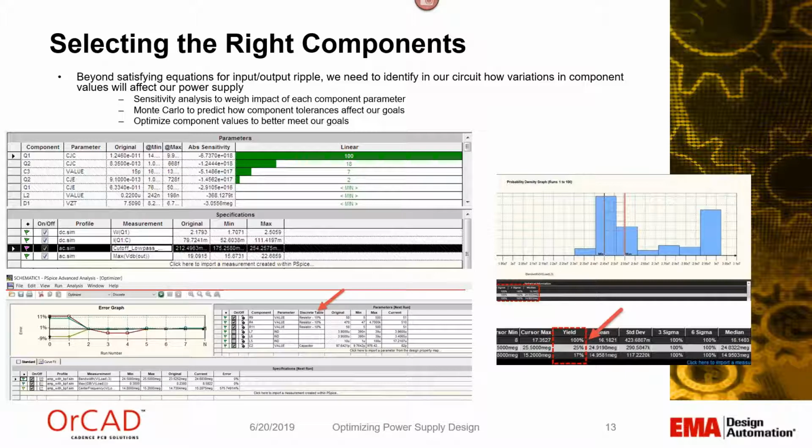And then in the table below, in the image below, we can use what we call our real-world component table. Assign a list of capacitor values, resistor values, and inductor values that you're willing to use, and you can use our optimizing technique to minimize the difference between your goals and what those components can give you. That way, it will do the work of solving for what component values can best fit your circuit. Another reason to build this simulation is that if you need to make changes in the future and change your goals, you can easily reassign different goals and optimize the different component values.